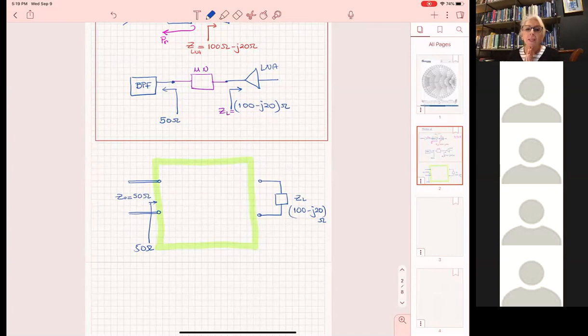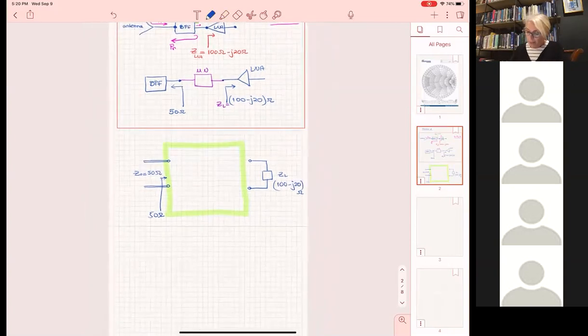100 ohms. So would we need a quarter wave to transform that? Excellent. Yes, absolutely. Okay, so let's try to do that. The first thing is that without even the Smith chart, I can do this quickly. What I decided to do is to use 50 ohms as my reference, and then I will do both here and in the Smith chart.